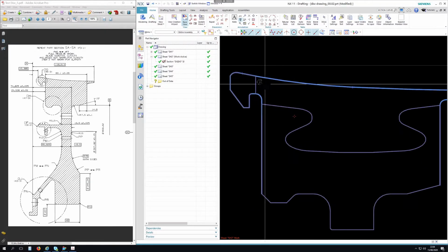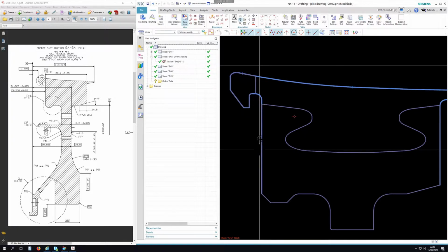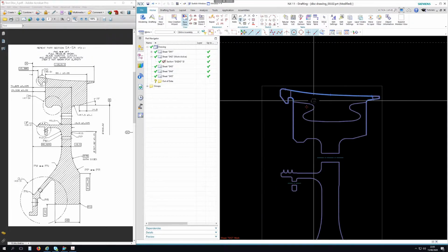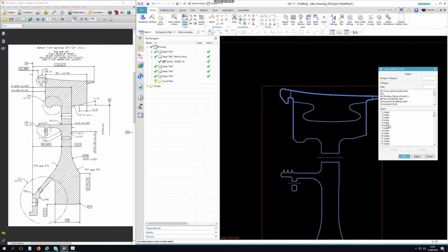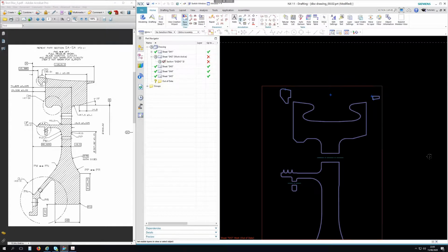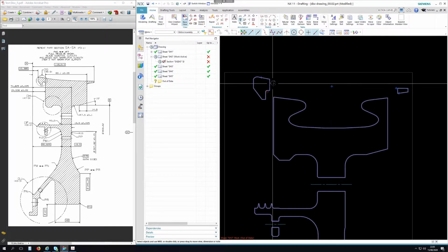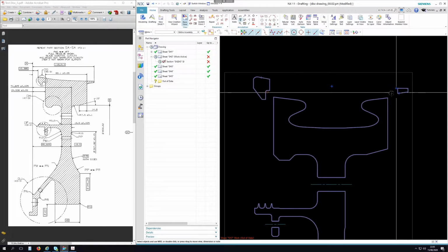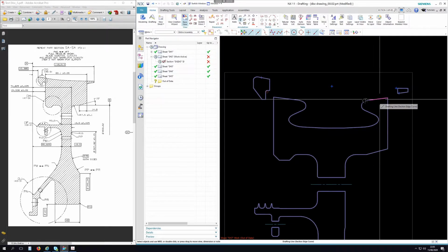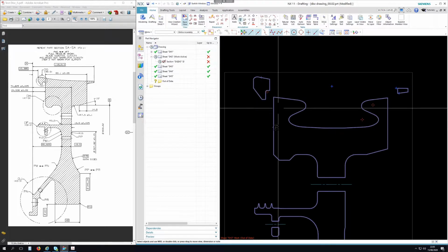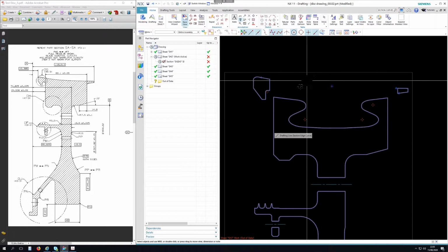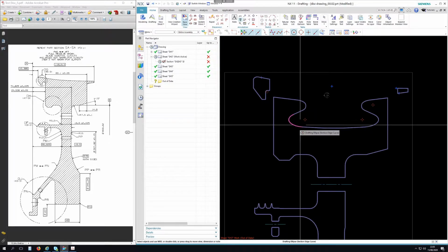And if you look now, we've got lines on top of lines here. I think I put this on layer 20, so visible in view. Let's click on this view, and for now, let's make layer 20 invisible. So this is the original line work, and I don't want lines overlapping lines here. I need to get rid of these original lines and put my lines in instead. If I've got lines overlapping lines, when you come to section it, it probably won't section very well.